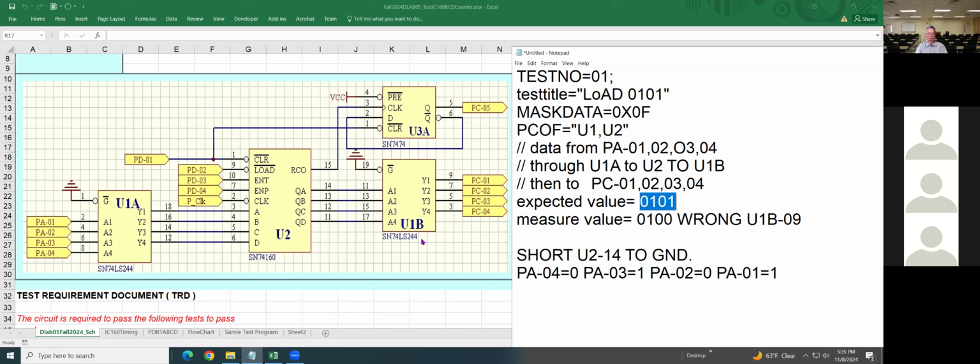Wouldn't you check, the first thing you always do is check your ground and your power source, right? On any IC? For sure. You check power pin 16 or ground pin 8, for example, or pin 14 or pin 7.